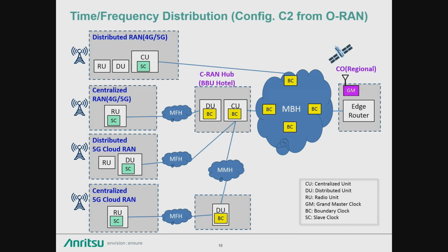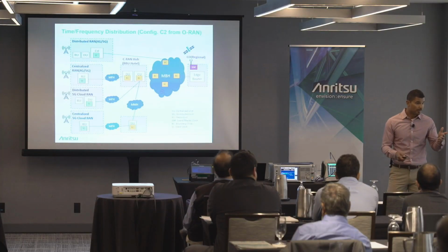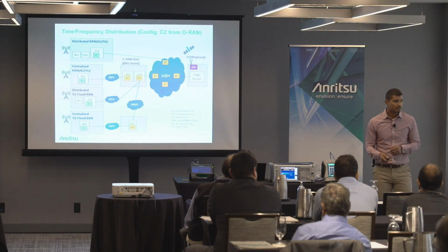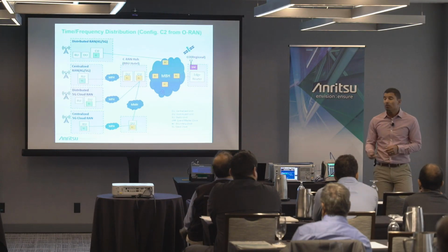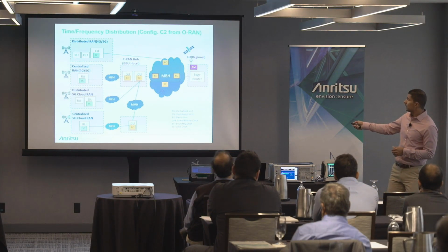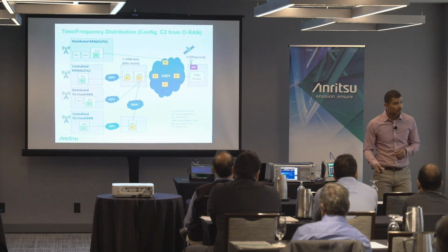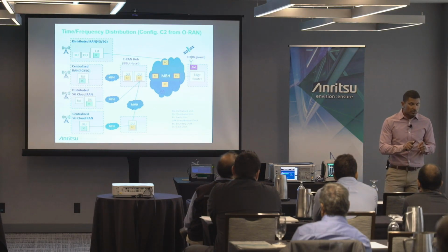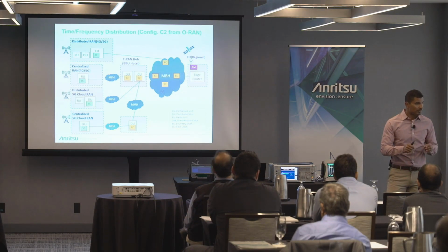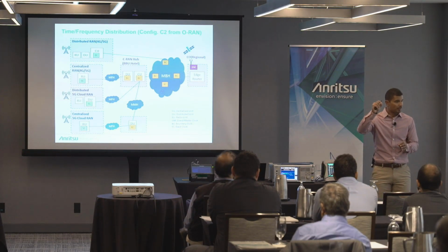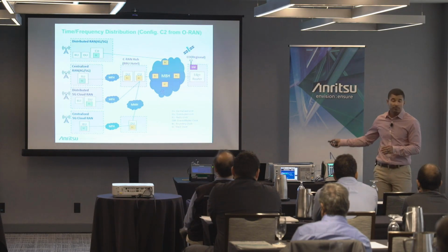Also, you have to worry about the satellite link. If that is, let's say, over 900 meters, then you are off already. Well, with the satellite link, are you talking about the communication over the air to the grandmaster here? That will take more than 3 microseconds by itself. That's only in relation to the timing reference. So the satellite's providing the timing reference to the grandmaster, and the grandmaster now becomes the PRTC, the primary reference timing clock.